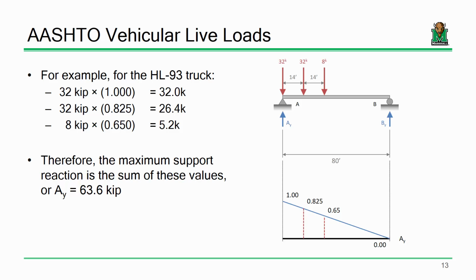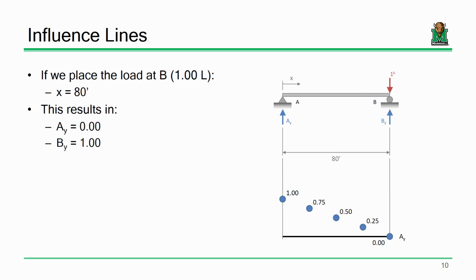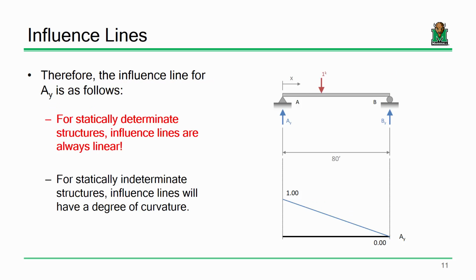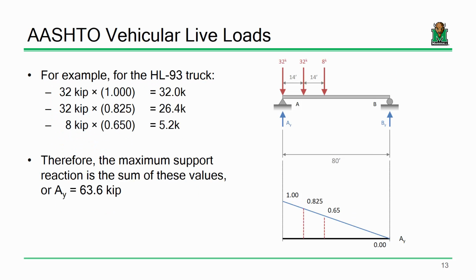Ignore what's going on with the slide, and let's just do a basic example. Let's say I put 20 pounds right smack dab in the middle of this table. How much goes over here and how much goes over here? 10 pounds. Let's say it's 180 pounds. How much goes here and here? Okay, now how are you doing that? You're just taking it and dividing it by 2, right? I propose what you're doing is you're taking it and multiplying it by the value of the influence line at the center, 0.5. Once you've got the influence line for a point, you can determine the reaction due to any load.